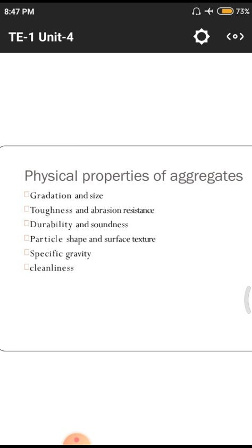But in Iceland and other areas, they have minus degrees Celsius temperature, so they have to lay the roads in a separate manner. From state to state and country to country there may be temperature variance, and according to that the durability properties also change. We have to observe in what condition we have to construct the road, what the purpose of construction is, and the average annual temperature we have to take. For those only, we have to construct the roads.